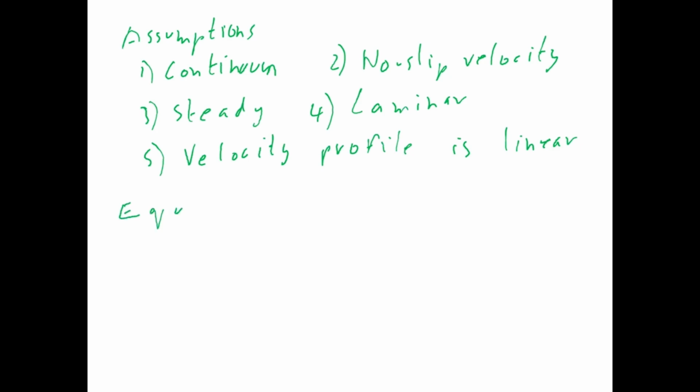So the last thing you want to do before starting to solve is at least list out the laws or equations that you're using, right? In this case, the only equation that we have covered is that related with Newtonian fluids, right? Which is shear stress is equal to viscosity times the velocity gradient, du dy, right? So in this case, you have